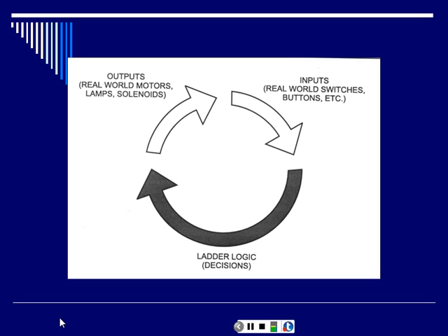For those of you that have had motor controls, remember having to wire up the relays because the magnetic contacts had to be energized to keep it on? We no longer have to do that. If I put a relay out there, the PLC knows that if this is on, this needs to stay closed. So it does that as logic now instead of an actual component. So you won't hear it click, okay?